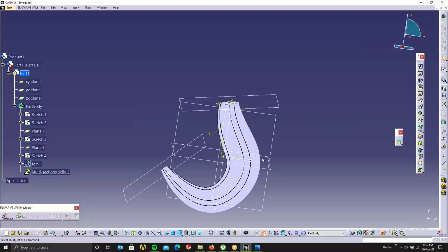Like this, you can create the hook. So just try it. So probably the confusions you would have had is this one, right? This plane and creating the circle. The second confusion you would have had is about this closing point. This you would have missed out. And the third one would be that ratio, instead of tangency and curvature. Those three things are very common mistakes people make.